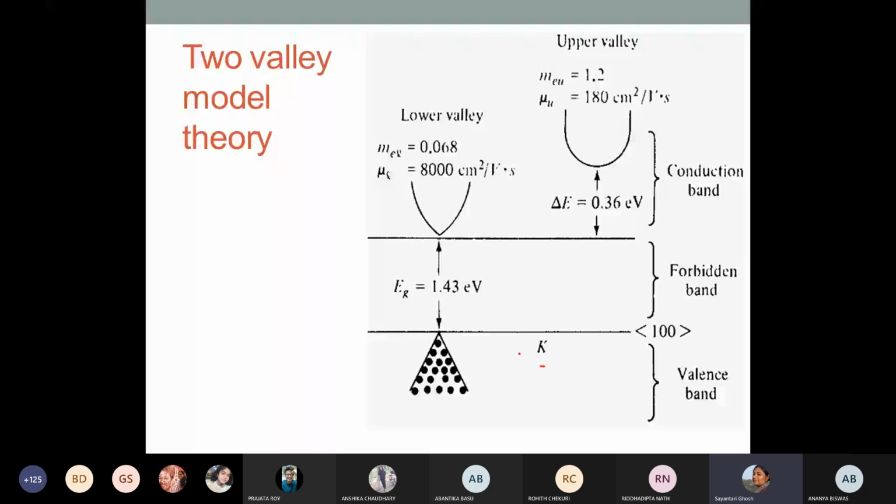So gallium arsenide is used to make devices like LEDs, or light emitting diodes, because if the conduction band and valence band have their maxima and minima at the same value of K, then the transition of electrons or holes from one state to another is transformed not into thermal energy but into light energy, and you can get light out of it. That is why we learned about gallium arsenide in the first place.